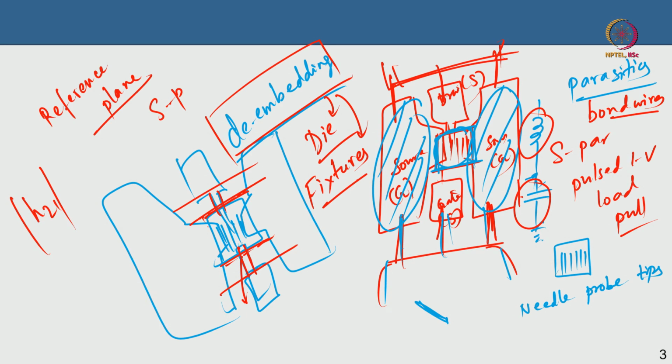Essentially we will try to see how the small signal model of a device is built conceptually, from the fact that it's a nonlinear device. A transistor is nonlinear, even a diode is a nonlinear thing. So from there we linearize. That means we are talking about small signal, where the magnitude of the signal is small enough that you can linearize it around a certain point. You can treat the variations as linear around that small delta variation. So we are not talking about large signal.